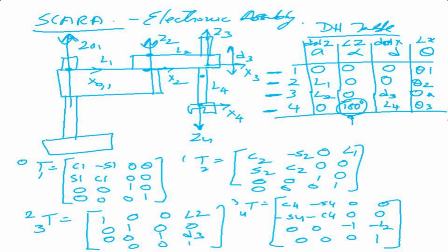There is no angle between them, they are parallel. There is no distance between the x-axes. Okay, so it is 0 and this is theta 2. Now just note that I've taken my origins here and here, so z1, x1 and x2 are aligned. If I take my x2 here, then a particular distance will come there. Actually the link has a thickness, so some distance should be there, but just for simplicity we are saying that that is not there. Okay, just note this.